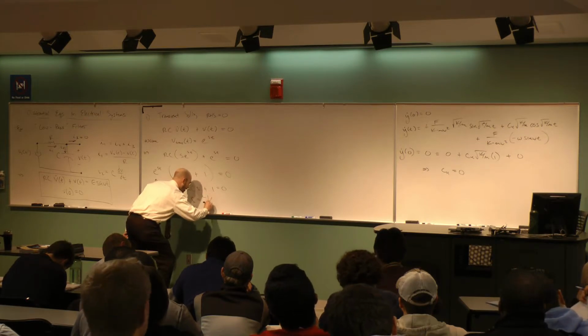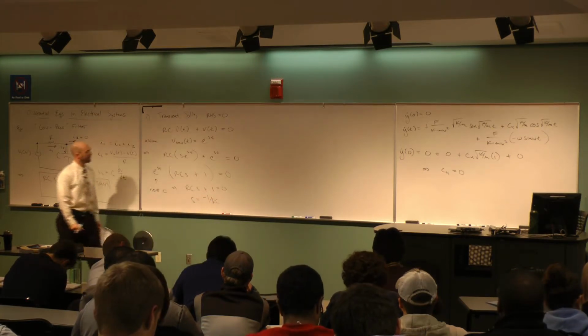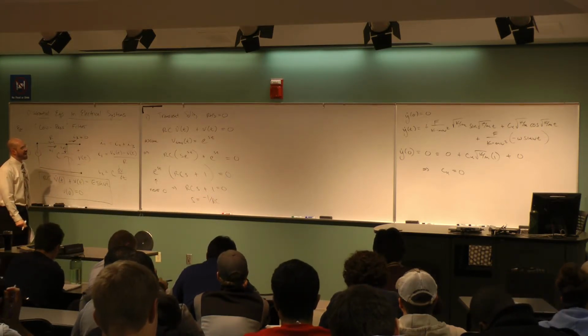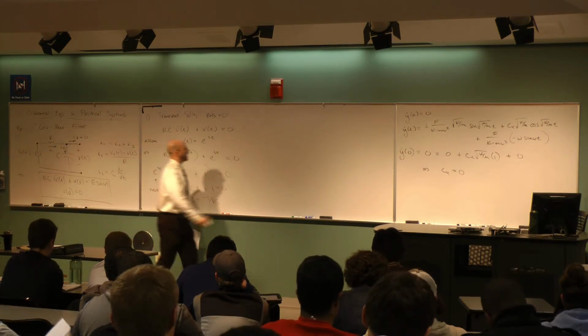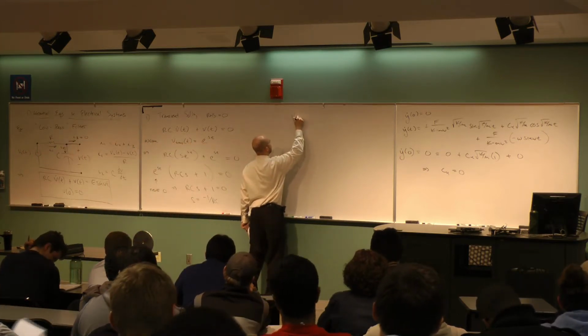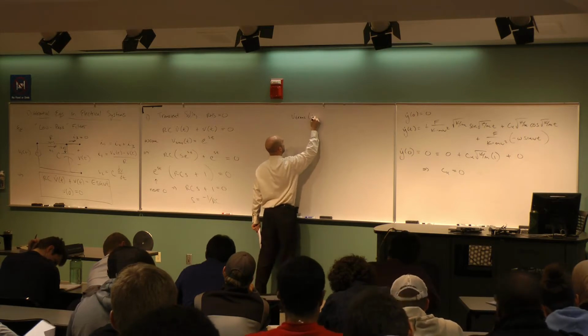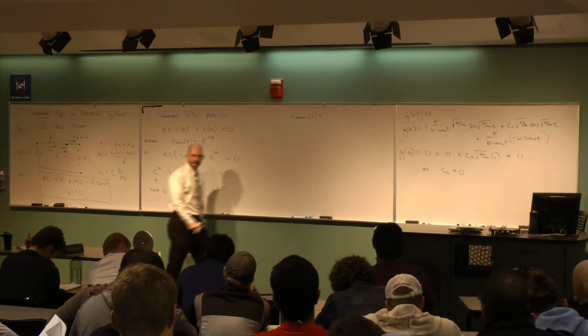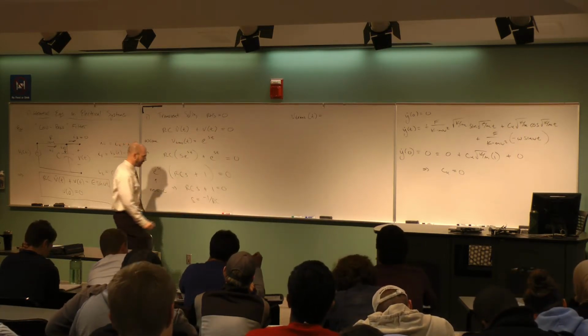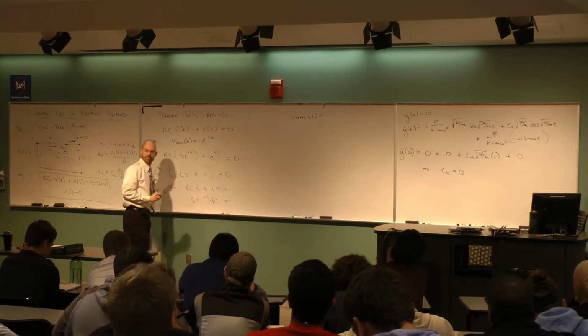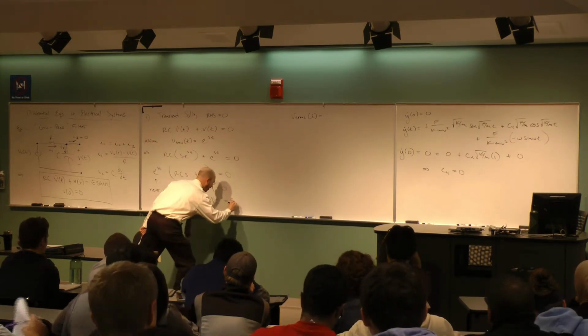Yeah, it's minus 1 divided by RC. Okay. So once I have the S value, then how can I write the transient solution, V transient of t? Plug in the S, okay? So this is S. How many S's do I have? 1. So you can call this S1.